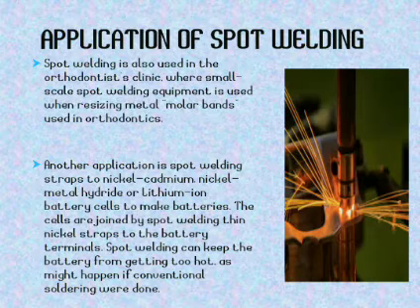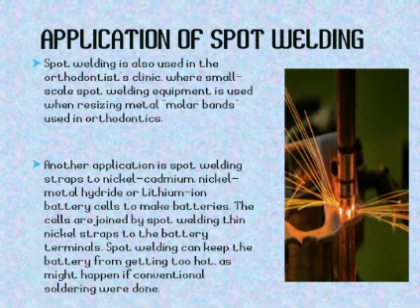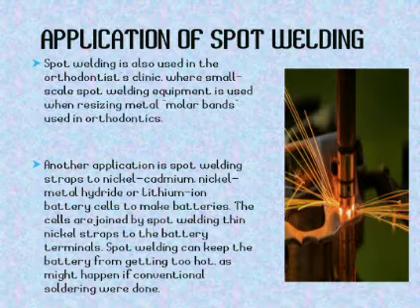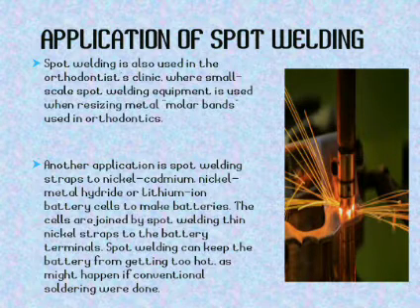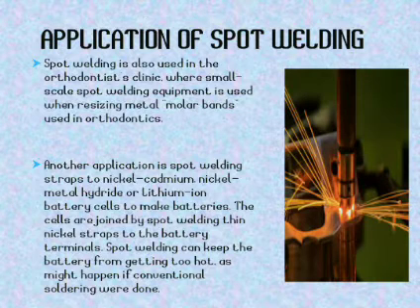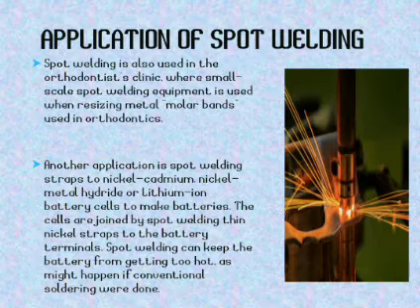Another application is spot welding straps to nickel, nickel to cadmium, nickel to metal hydride, or lithium ion battery cells to make batteries. The cells are joined by spot welding thin nickel straps to the battery terminals, and spot welding can keep the battery from getting too hot, as might happen if conventional soldering were done.